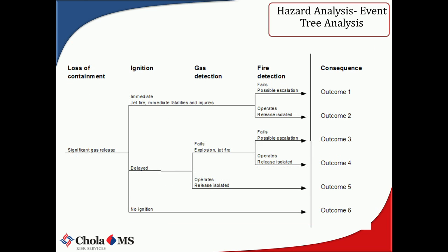Okay. Another one is the event tree, where you are now identifying hazards and consequences. Look at the difference. It goes in a different direction. In a fault tree, for example, if there is a fire which has occurred, you start from the fire. You have a release, you have a source of ignition, why the release has happened, what the various causes are, and from where you got the set of ignition sources.